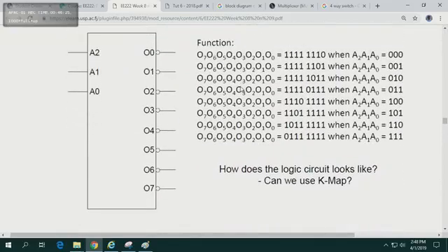All right. Now, let's have a look at this decoder. You have 3 inputs. But how many outputs? 8 outputs. Now, what does the bubble mean? The bubble means that at one point in time, only one output will be off. All the other outputs will be on. Because the initial theory is that only one output will be on, and all the others will be off. But if you put a NOT gate on each line, obviously everything's going to flip over. Yeah?